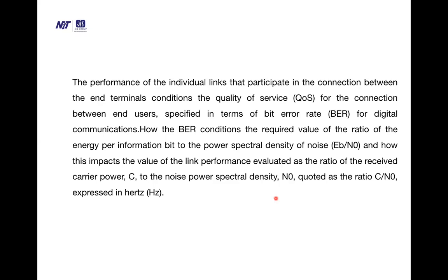The performance of individual links that participate in the connection between the end terminals conditions the quality of service, QoS. QoS determines the quality of the signals at the time of uplink and downlink, and at the end portal how the signal is coming. And bit error rate, BER, is very important for digital communication.